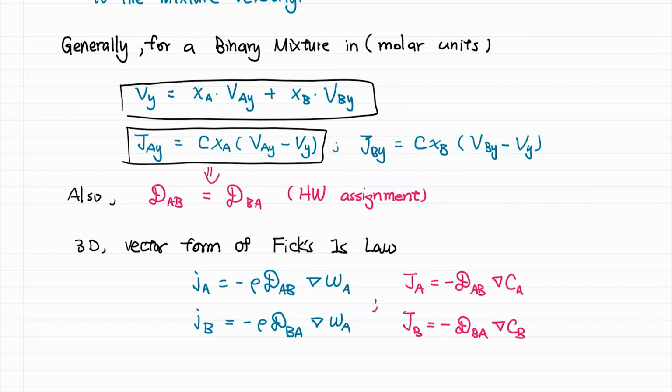Okay, so you can see again, the most important thing we want to introduce here first is Fourier's law of heat conduction and Fick's first law, which describe the heat and mass flux as a function of the gradient of temperature or concentration throughout a particular length, okay? And they are related by the thermal conductivity and the diffusivity.